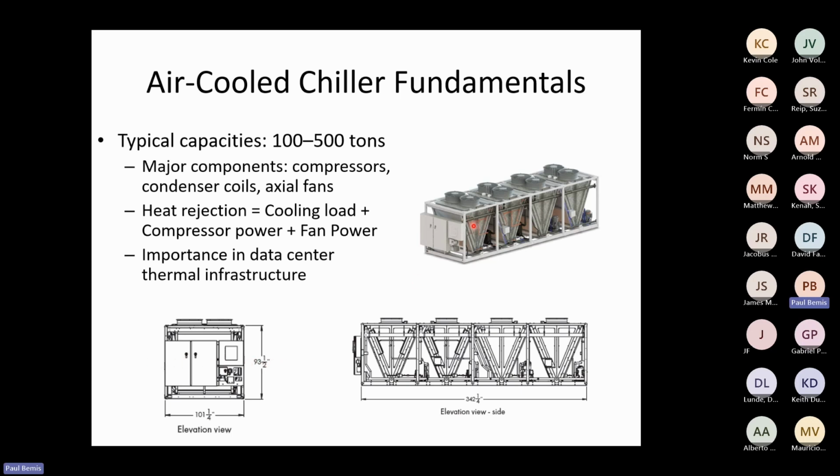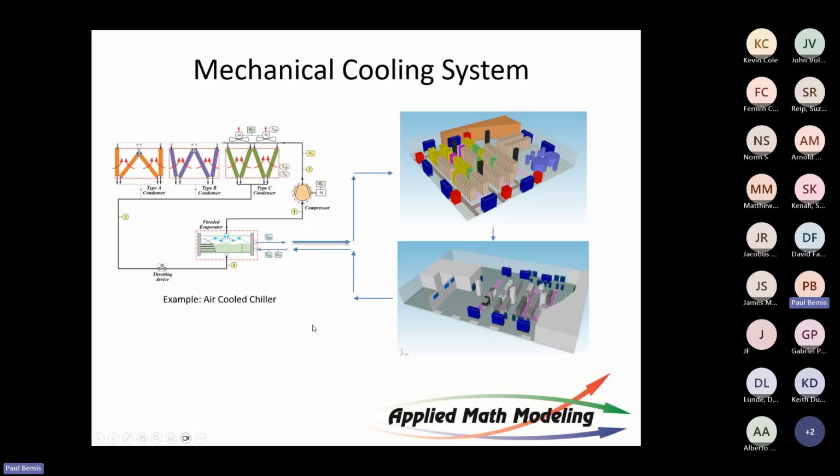These devices, their performance is correlated to average inlet temp, and that is something that you're going to want to calculate using CFD. And essentially, you want that at the midplane. You're trying to figure out what the approximate inlet temperature is right about at the middle of that chiller, okay? So average inlet temp is quite important because that drives performance. You'll see why in a moment. But keep in mind these numbers. Look at your build out, look at your spec sheet for the device, size this appropriately. I'll come back to this later, but I just wanted to point that out right now.